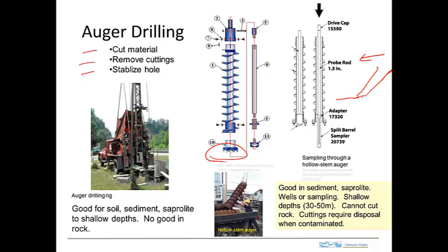And so if this is the bottom of the hole, as this thing moves laterally, it cuts, and the cuttings come up like that. Okay, so what's happening is right here at the bottom you have shear, and this bit is shearing along the bottom and cutting this material, and then ultimately it'll lift it up out of the hole.